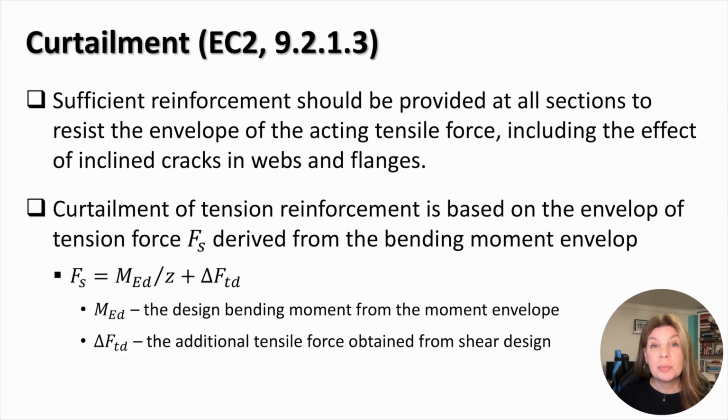Sufficient reinforcement should be provided at all sections to resist the envelope of the tensile force. This should include the effects of inclined cracks in webs and flanges. Curtailment of tension reinforcement is based on the envelope of tension force derived by adding the additional tensile force, delta FTD, obtained from the shear design to the tensile force developed in the reinforcement due to bending, where the latter is obtained by dividing the maximum bending moment in the section by the lever arm.